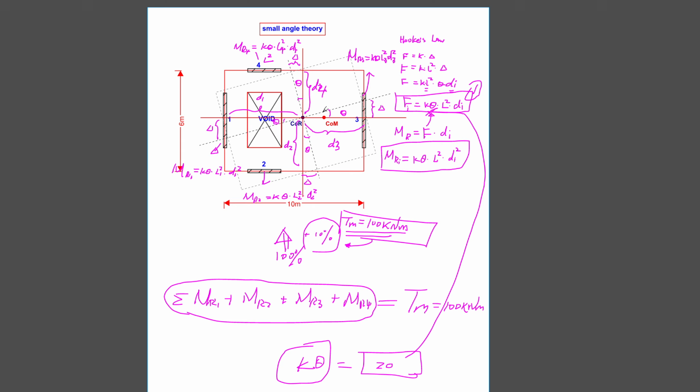That shear force comes from the 10% eccentricity, because the eccentricity causes a little bit of a twisting moment that is circling around all the walls, and we need to find out what forces are induced in each wall.